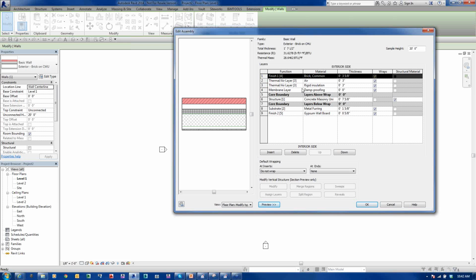Yeah, and I guess it's important to point out that this is built in inside of Revit, and it's new to 2012 or 13. I think 13 is when they introduced that. So from 13 to 14, you actually have the R values built inside the walls in this processing. And that's all coming from the materials parameter.